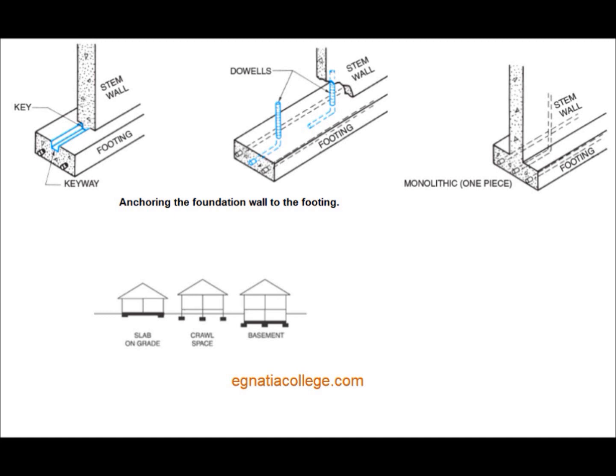footing forms. A complete set of construction drawings also includes sections that show the spread footing in greater detail. However, these drawings are often superseded by local building codes. Building codes for footings include such things as minimum permissible depth of footing, required strength of concrete for footings, the width of footings, and the use of keys or dowels made of reinforcing steel.